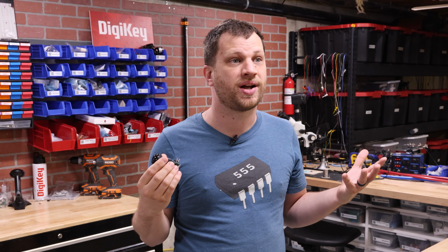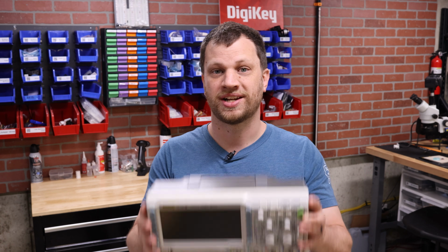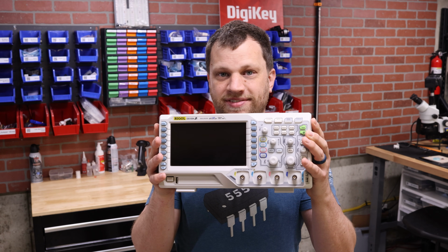One of the most frustrating things about being an electrical engineer is that we deal with invisible problems, and these can be really frustrating to track down and solve. Let's say, for example, I'm trying to read a push button with my microcontroller. When I press the button, my microcontroller reads 5 presses. Why is that? That's exactly the type of invisible problem that an oscilloscope can help you catch and fix.